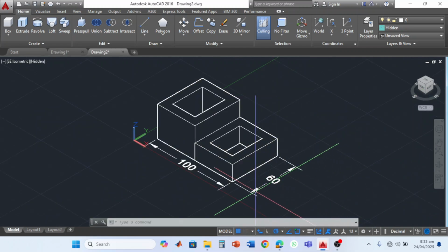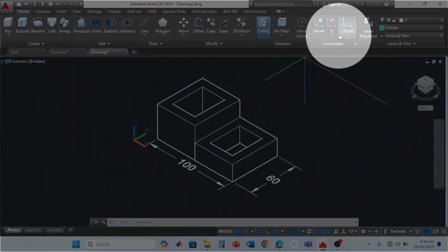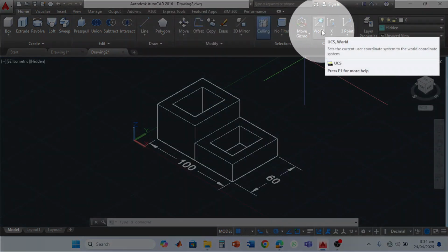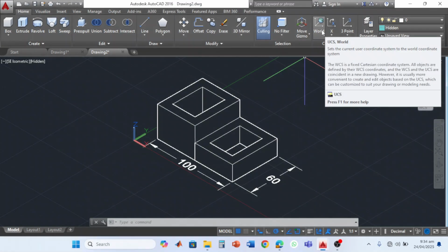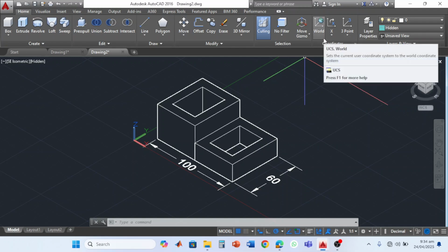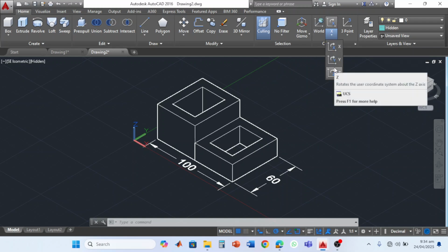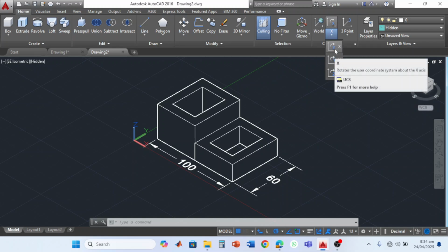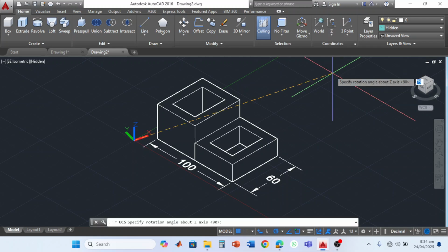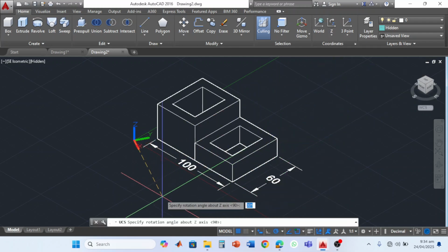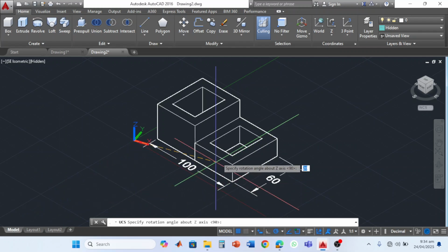Now in the 3D basic, we can add a dimension X and Y by this, but now here you have a universal coordinate system. There is one section for the coordinates. World UCS means standard. In spite of this World UCS, we can have another UCS also. We can have x-axis, y-axis, z-axis. So change the x-axis to z-axis. So we are rotating the axis about z-axis.